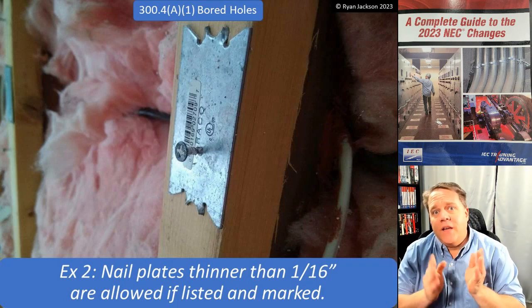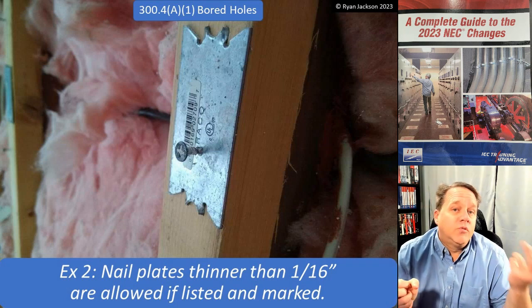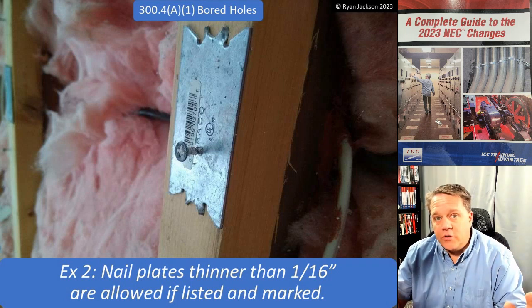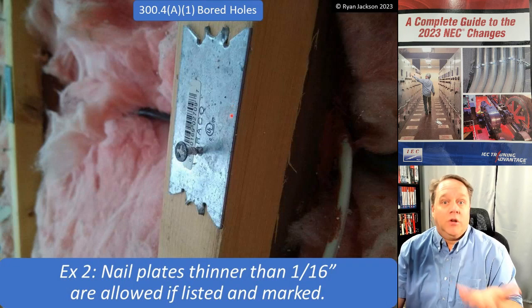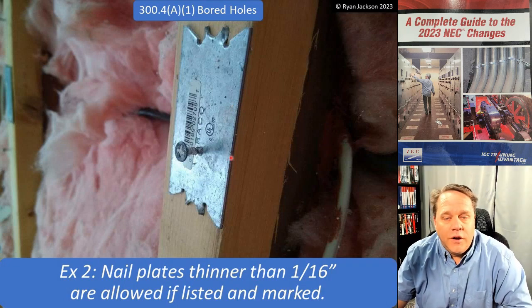If you buy the listed nail plates, then we know that they've passed whatever tests the UL standard has in place for them, and we know that they're going to be strong enough to stop nails and screws. Now, here we've got a drywall screw going through a listed nail plate. Look, I'm not going to tell you that this thing is a bulletproof vest. If you try hard enough with your drill, I'm sure you can get a screw through here.